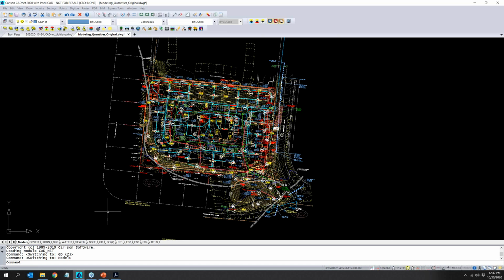The good thing is you should be able to find somewhere in here all your polylines and things. Are they going to be on good layers? Probably not. Are they going to be elevated? Maybe, maybe not. Is the geometry going to be good? Will endpoints connect? Will they be polylines? Probably not. So you will have to do cleanup. You will have to do elevating 2D to 3D.